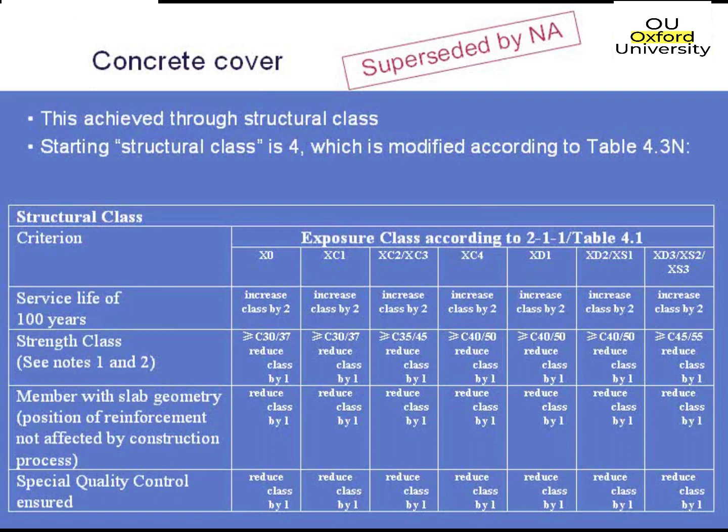structural class of 4. You start off with this structural class of 4 because the Eurocode tells you that you start off with a structural class of 4. So starting off with that, then if you've got a bridge, and you've got a service life of 100 years, you have to increase that structural class by 2.